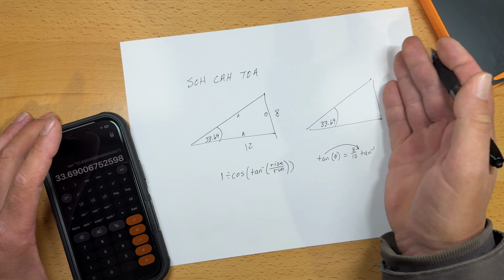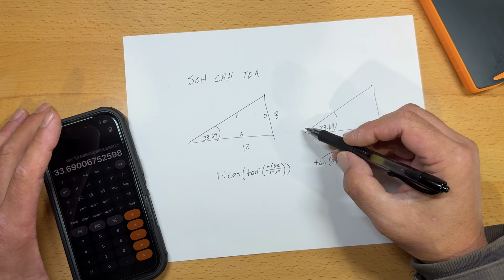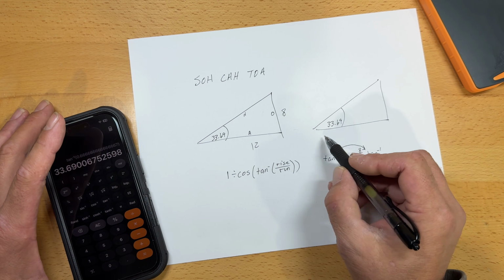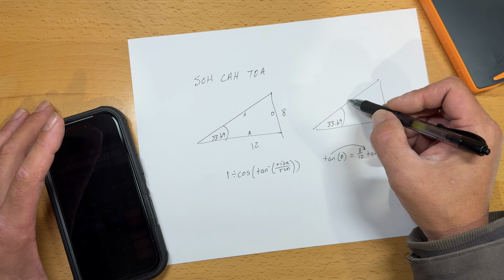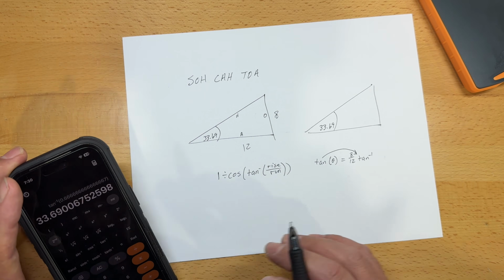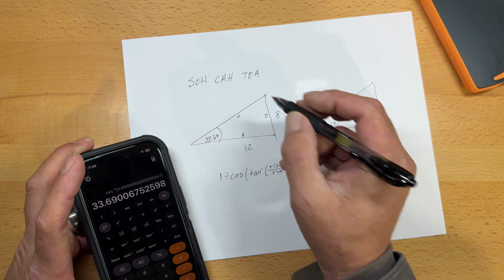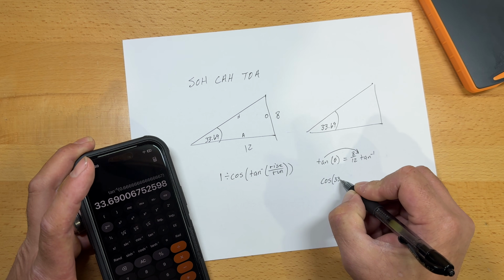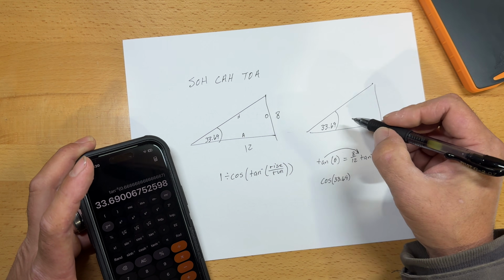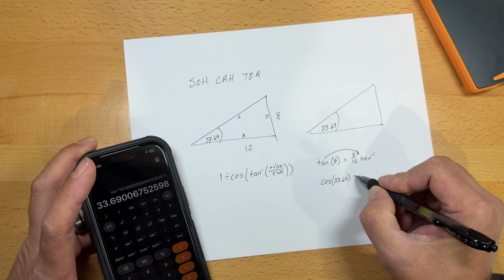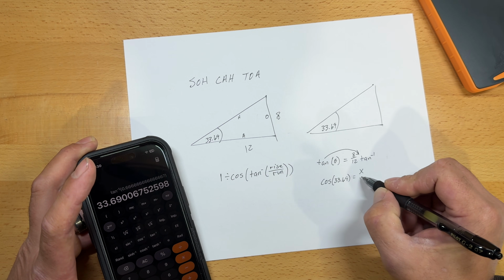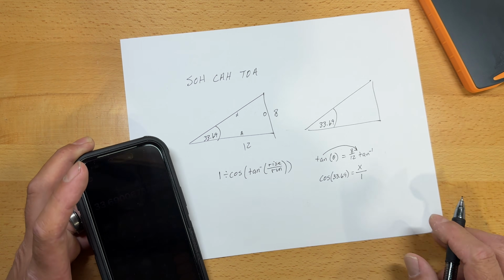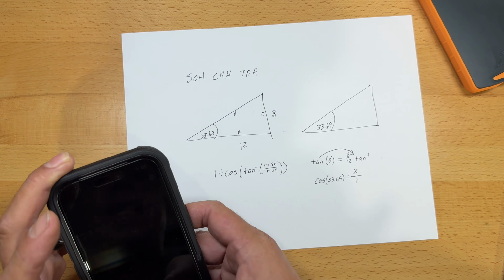Now we'll just move it over here. Consider this the same triangle. What we're ultimately trying to find is what the multiplier is for this side. So when we know the run, what do we multiply the run by to get the rafter length? So now, in order to do that, we have to change our formula. This is going to now be cosine, and now we know the angle. That's going to be 33.69. Will be equal to the adjacent side, which we are trying to find the value for, and it's automatically going to set the value for the hypotenuse or the rafter length at 1.